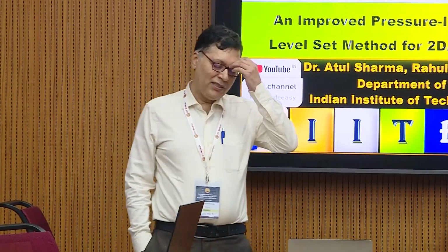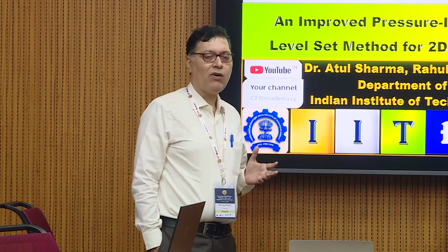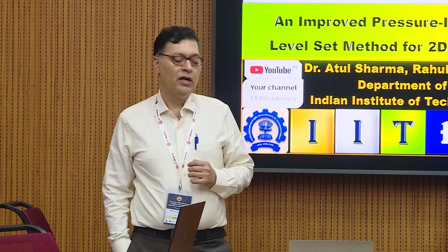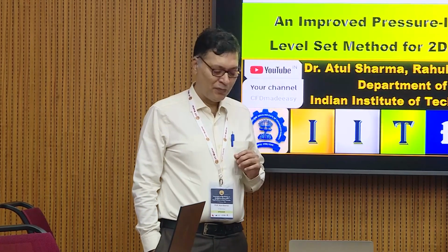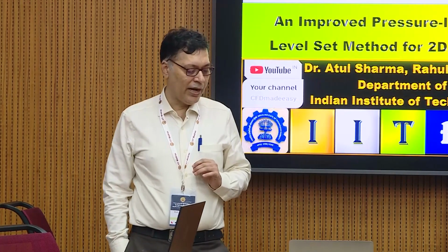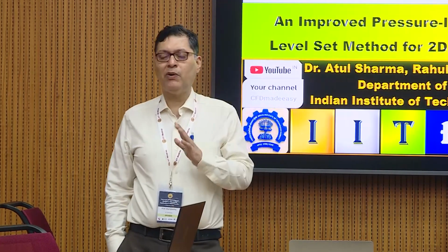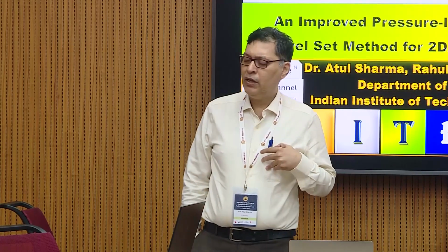Now as far as surface tension, force due to surface tension is concerned, it's a surface force, while commonly in computational methods it is modeled as volumetric force. A diffuse interface method is a one fluid formulation which uses single Navier-Stokes equations, whereas sharp interface method is a two fluid formulation which uses interfacial boundary condition as a jump in pressure or temperature for heat transfer problems.